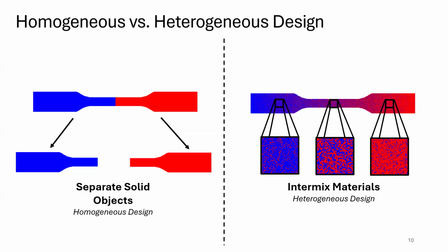So, okay, given that, when you were talking about the OpenVCAD setup, you had, as part of the compilation, randomness as part of the distribution. This is when you were saying like 80% blue. So if I feed your system the same specs twice, I should get 2 different things that have the same distribution, but may give me different mechanical properties. Yeah, so one of the things you can do in OpenVCAD is control the seed on the random number generator, and that's just for replicating things in the most scientific way possible.